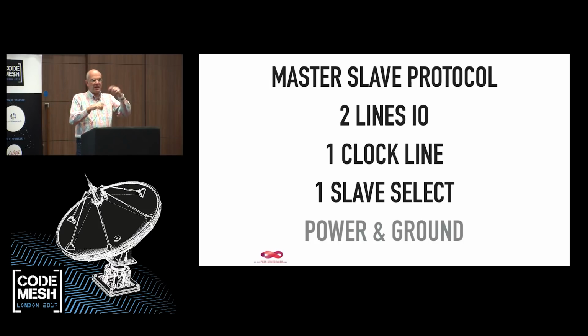And then you can configure like on what clock phase the bits get shifted and stuff like this, which makes it complicated again, by the way, because in the chips you get all 4 combinations of like first edge, second edge, phase shifted, polarity, and power and ground. I mean every PMOD connector has power and ground. So you have a 3.3 volt power on the connector actually.